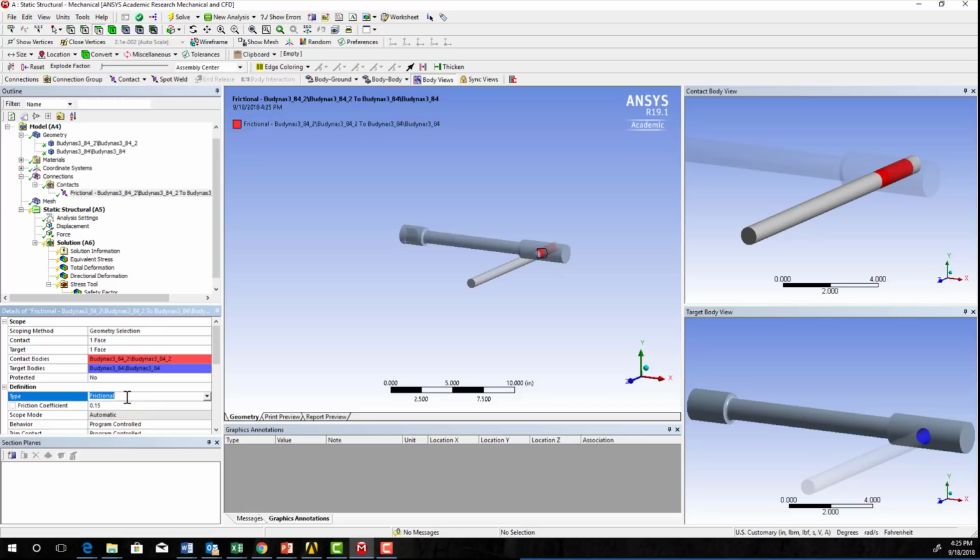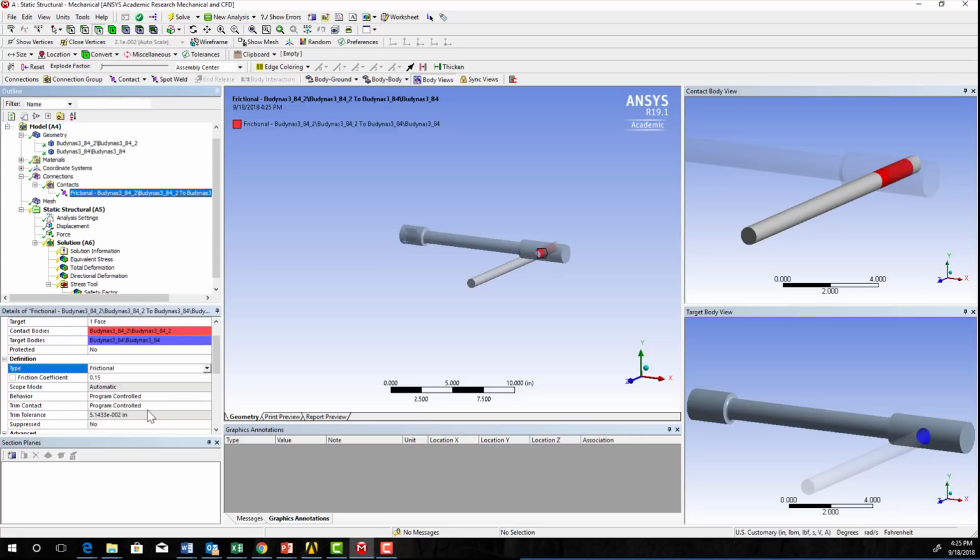If you're going to do a rough contact can be good. That allows it to do high friction contacts. Frictionless, you need to be concerned about whether it's going to be stable in the solution. But going to a contact point there, it starts to become nonlinear, and so the solution time is likely to increase. Okay.